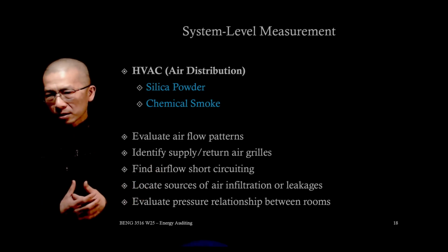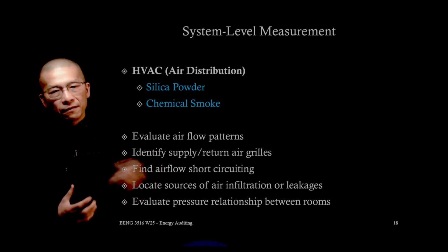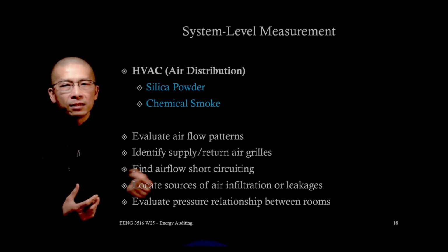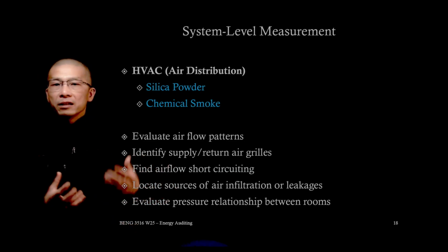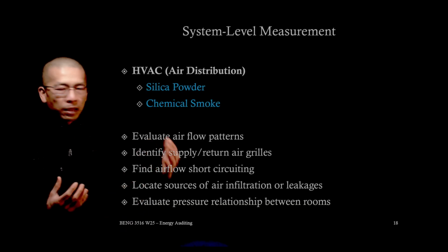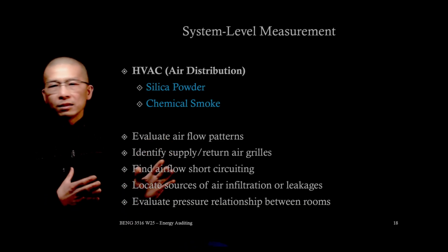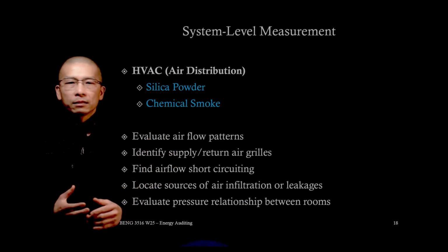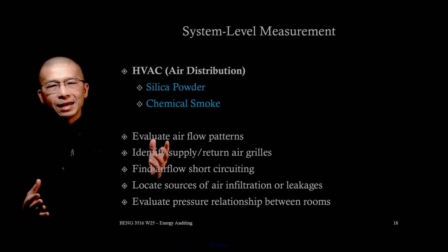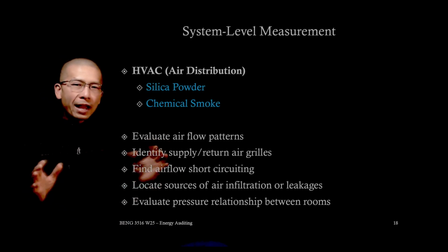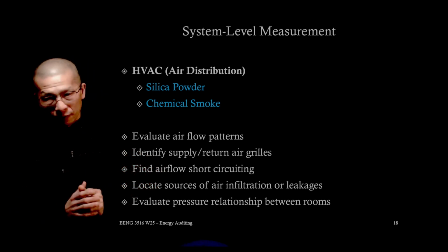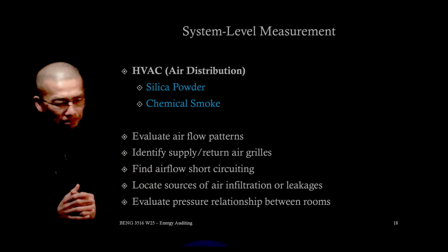Smoke also helps us locate sources of air infiltration or leakage within the space. Unexpected smoke movement near the door, near the partitions, joints, ceiling penetrations may indicate pressure imbalance, right? So we don't want any of those unintended airflow paths, right?